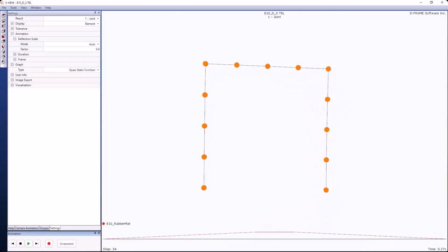And there are lots of different applications for quasi-static analysis beyond just testing this type of nonlinear material. I think this is just the most tangible from a visual perspective, but I use it often when I want to sequence different loads. So maybe I want to apply a gravity load onto a structure and then ramp up a vertical load. A pushover analysis, for example, can be accomplished through this type of analysis and loading functions.